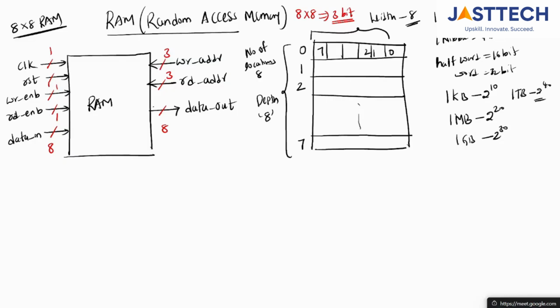Okay, so we are designing the RAM, no? So here there are steps. What is the first step? First, you need to make write enable equal to 1. Okay, write underscore enable equal to 1. We should make this signal 1 in order to write any data into RAM.